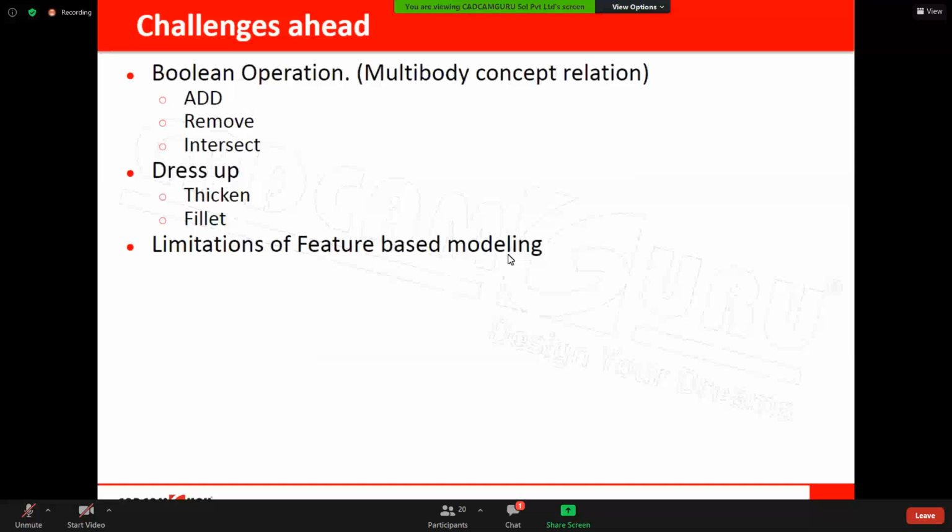Can anyone tell what is feature based modeling? We add features one by one, giving dimensions to them. Do you have any experience of what will happen in feature based modeling if any particular plane gets deleted? The parent child relationship will break, right? Correct.